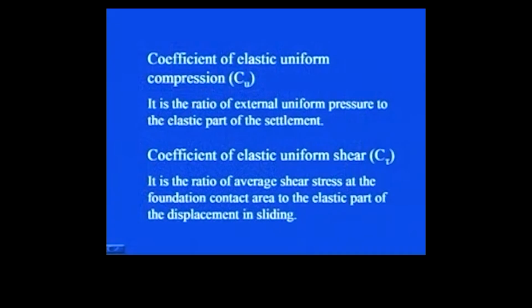As we discussed when we were discussing pile foundations, there is elastic and plastic settlement. So in this case also you will have elastic settlement as well as plastic settlement. So in case of the elastic uniform compression coefficient, it is the ratio of external uniform pressure to the elastic part of the settlement. Then the second one is the coefficient of elastic uniform shear.